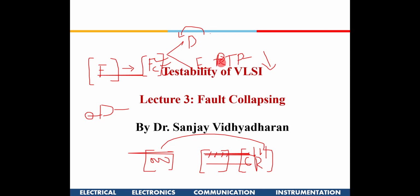What we are going to create is a random test pattern, and for each random pattern we'll keep ticking. Once one particular random test pattern has been applied from this easy list, how many have been killed in one go? Maybe 3 faults have been detected, or 5. So we just keep removing those from the list. Then we go to the next pattern. It is not done in a sequential manner. That also we will discuss, why random test, what's the advantage here. So we'll keep doing random test patterns and cover all the faults out here.